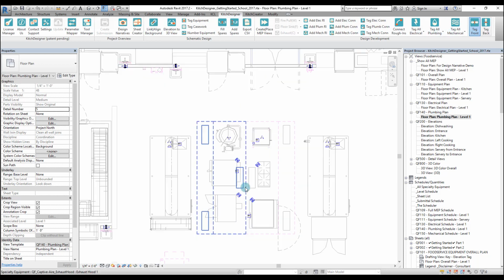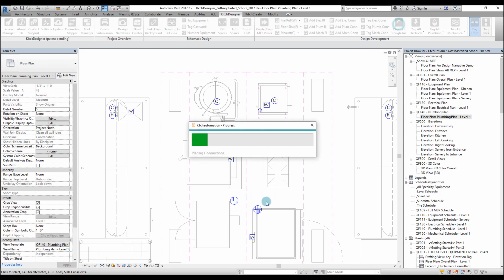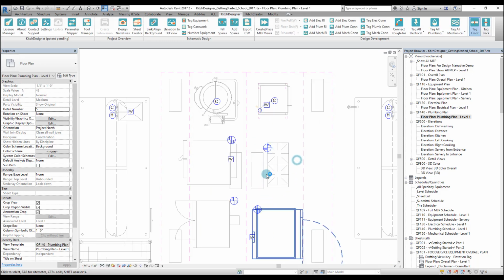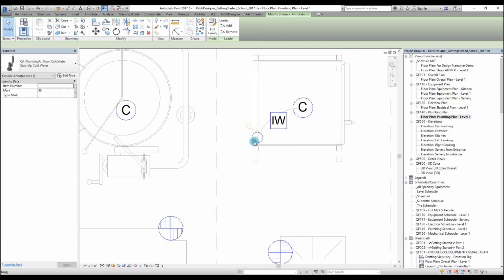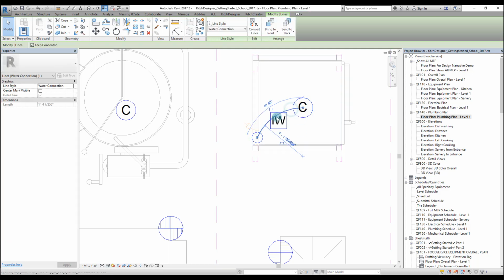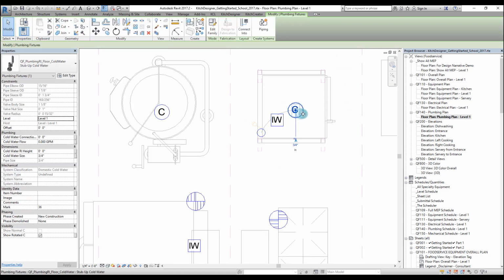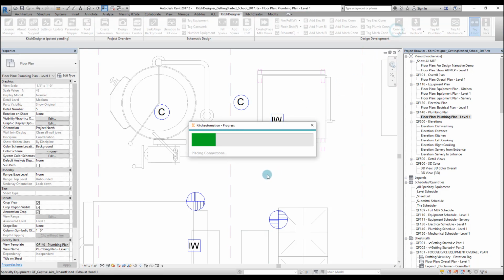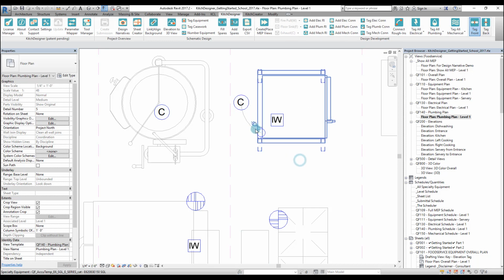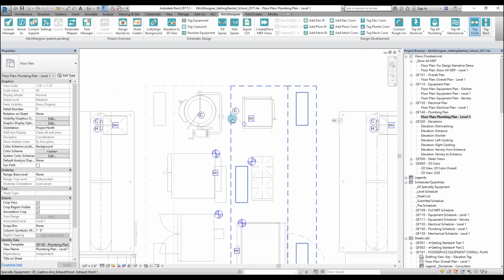And then we're going to connect them together. And here you go. Here's our roughin, here's our connection point, and here's our arc that connects it together. If this roughin location is not optimal, we can move our roughin and press the Connect Roughin tool again, and our field piping or field wiring will change.